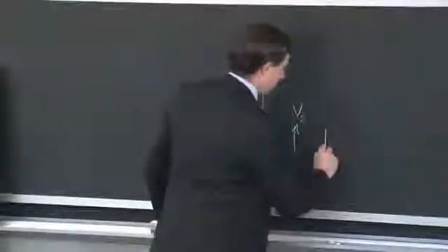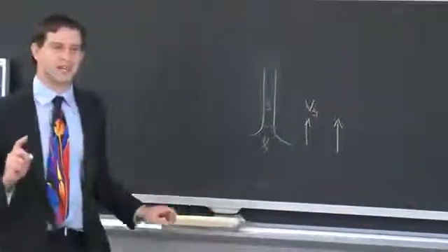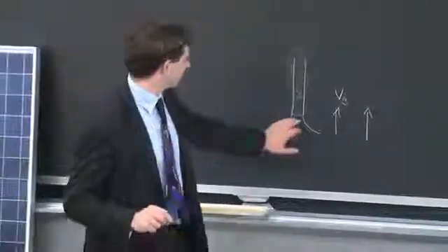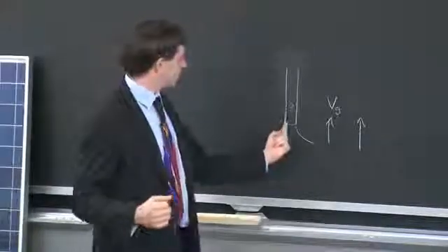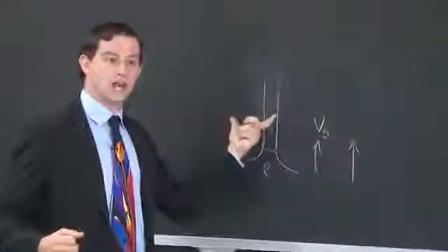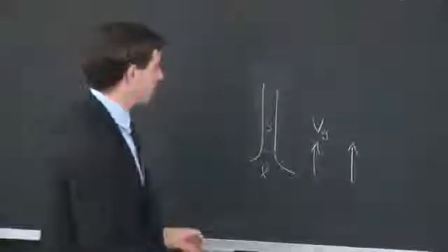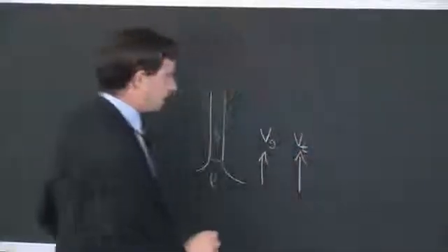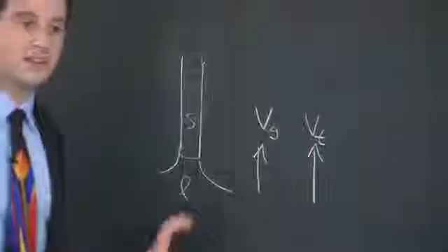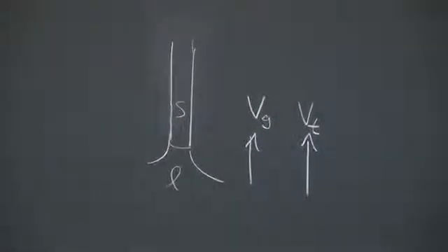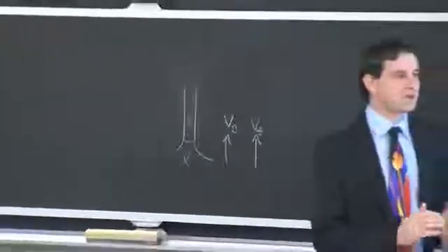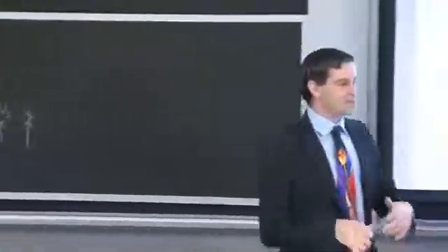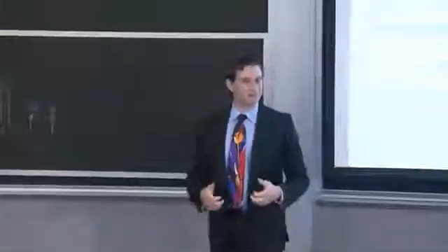And the direction of latent heat of fusion extraction. So you have liquid silicon solidifying here. During the solidification process, there is heat released. And that heat has to be conducted up the solid and then radiated outward from the fin, from this thin ribbon. So the direction of heat extraction is also parallel to the direction of growth. What that means is the growth velocity will be limited by the speed at which you can extract heat up the ribbon and then radiate it outward. So there are many ideas tossed around about potentially growing in media that are able to extract heat faster than the radiative transport.